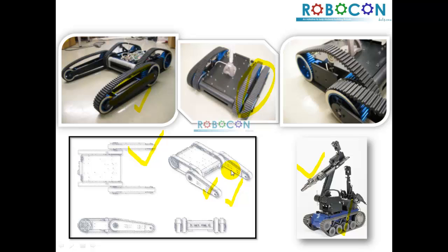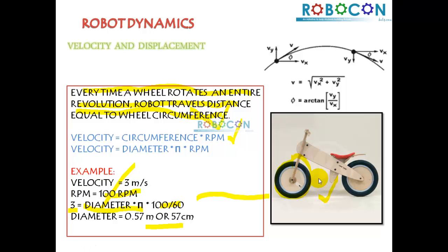So it becomes easy for the robot to climb any staircase. Another example of extension of this wheeled robot is using idler wheels. You can transmit motion from the rear wheels to the front using again a simple belt. Here you can see what kind of different configurations you can find using simple wheeled robot systems.